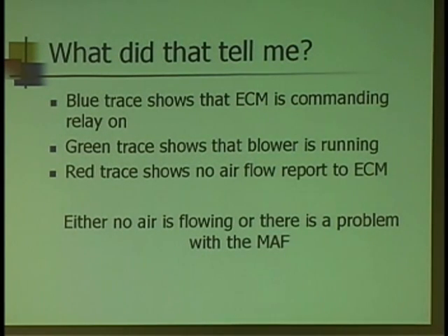What did the MAF sensor look like? Didn't change. So I either have what? A problem with flow, or I've got a problem with the MAF. So what would you do next? How about we just uncork the pipe and look at it again?